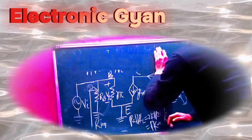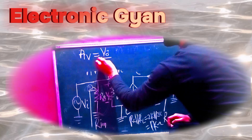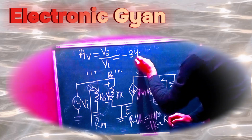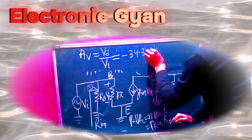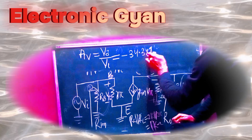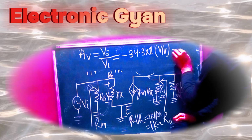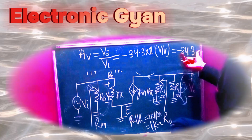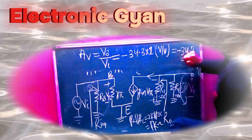So therefore overall voltage gain is obtained as AV is equal to V0 by Vi, which is equal to minus 34.3 into 1. Okay, so 1 is in kilo ohm, 34.3 is in milliampere per volt. Milli and kilo will get cancelled out and we are left with volt by volt. So therefore we got voltage gain as minus 34.3 volt by volt. This is the voltage gain of the amplifier that we got.